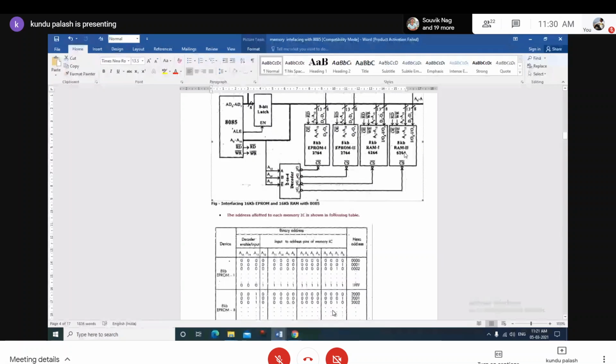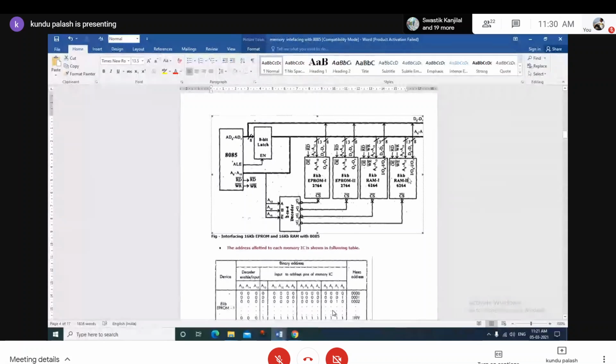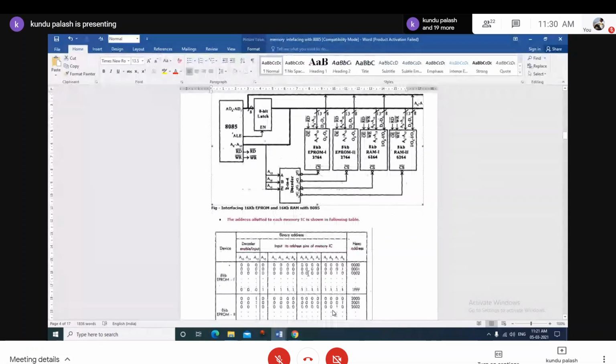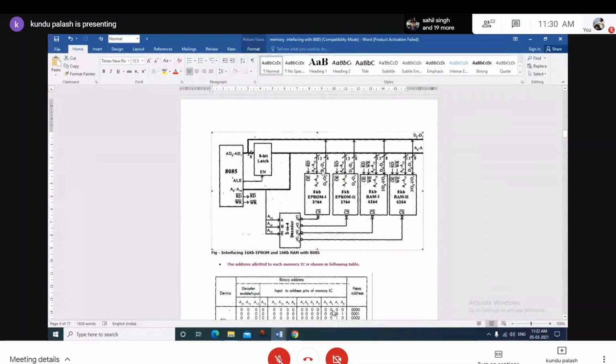That means, according to this information over the address signal, the memory chips will be selected according to the truth table. But the other address lines are directly interfaced, leaving A13, A14 and A15. What are the rest of the address lines? A0 to A12. That means 13 address lines, marked over the bus line 13. These are connected to the 8 kilobyte. To uniquely address any location within this 8 kilobyte EEPROM 1 block, only 13 address lines are required, not more than that, because 2 to the power 13 is equal to 8 kilobyte.